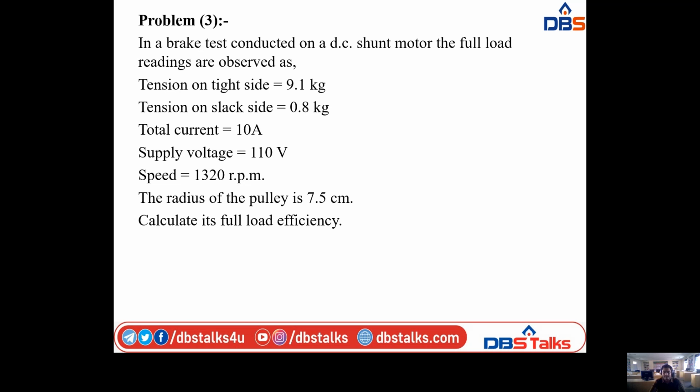And we have to calculate the armature current. So armature current IA, for the shunt motor we know the formula, IA is equal to IL minus ISH. They already given IL is equal to 25 amperes minus ISH, just now we calculated, that is 1.25. Finally we have the armature current is 23.75 amperes, and coming to armature copper loss, you know the formula, that is IA square RA. So here IA is 23.75, substitute here 23.75 whole square into RA value they already given 0.3 ohms. Substitute here, finally we have the armature copper loss